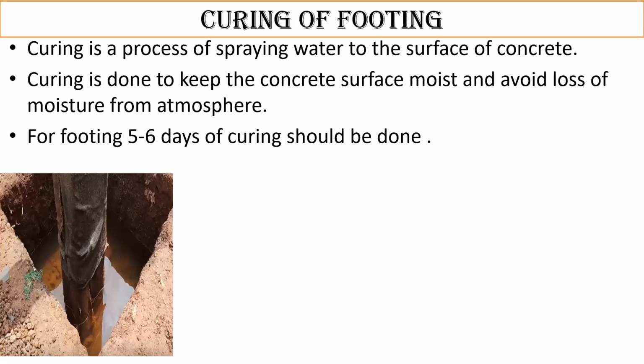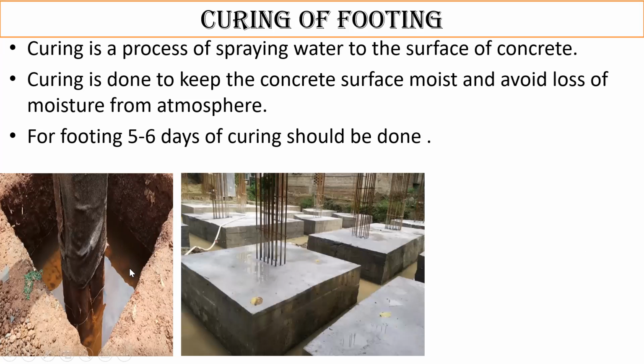So this is how it looks. We have done the footing casting. Now we are keeping the water here, right? This water, even if sunlight comes, if this water is utilized, or if this water is evaporated, it doesn't matter to me, because the water which is inside the concrete, that should not be evaporated. Because of that reason, what I'm going to do, I'm going to pour the water into this footing, so that the loss of water will not happen from inside the concrete.